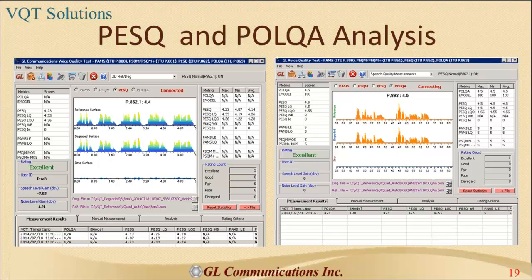The main differences between PESQ and POLQA: PESQ is still a great algorithm, ITU P.862, and it's used for PSTN and mobile networks, and it still works. Once you get into VoIP, and especially into wideband VoIP, like VoLTE, voice over LTE, which is AMR wideband, PESQ has some problems.